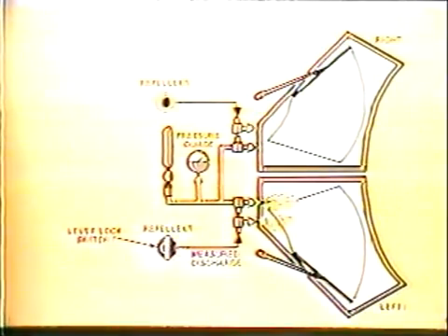Depending upon airspeed and rain conditions, each actuation should be adequate for 2 to 5 minutes. Approximately 75 applications are available in a fully charged repellent container. Rain repellent should only be applied in heavy rain with the windshield wipers on, and should be applied to only one windshield at a time.